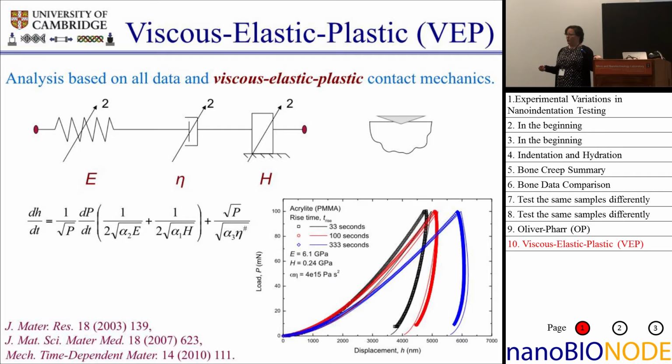It gives us the modulus, again, based on the same Sneddon elastic expression, and then we get some sort of a hardness and some sort of a viscosity. This is a pretty toy model. It's just meant to give these sort of three different time-dependent deformation modes.